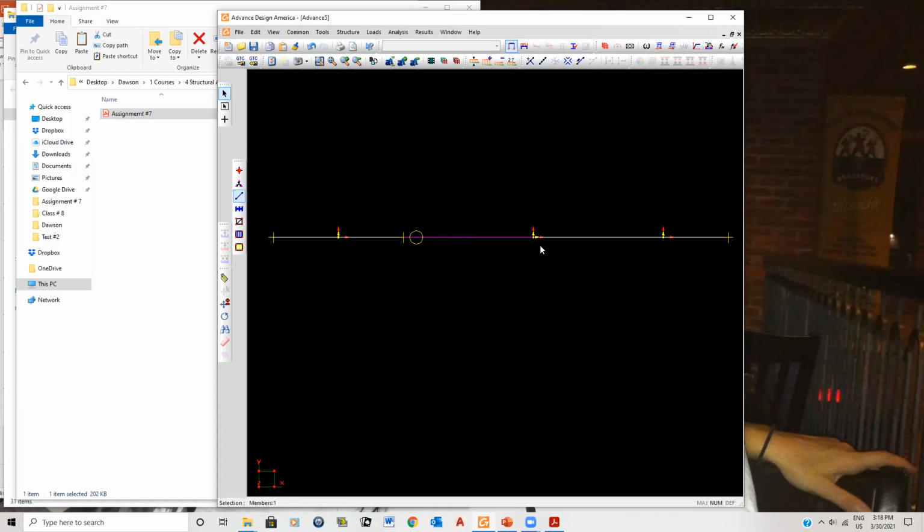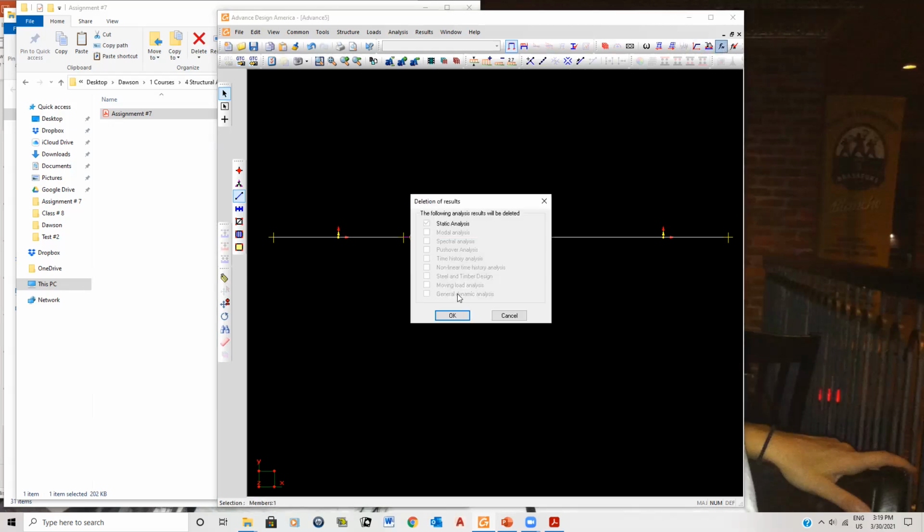Keep yours at the American one. Run your analysis with the American one, the A992, that's what you have on this example, right? Yeah. Okay, so keep your results, and I'm going to run this one with the 350, the G40.21 350W, and I'll show you where the difference is. So now I'm going to run the analysis, I have to rerun it because I modified the material.